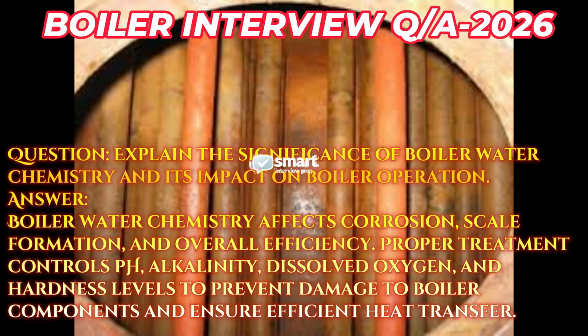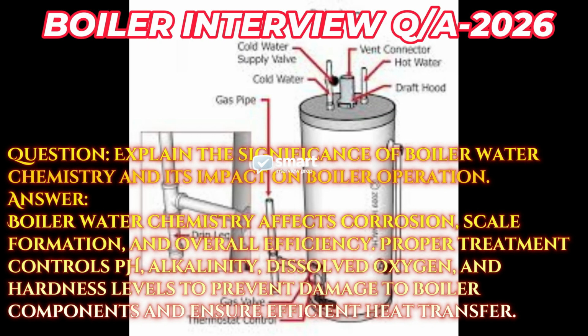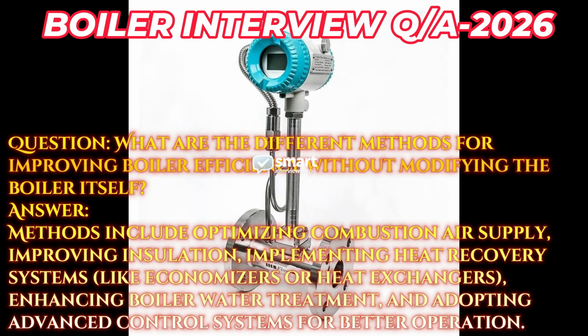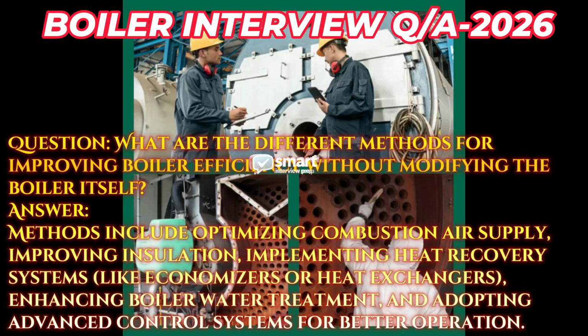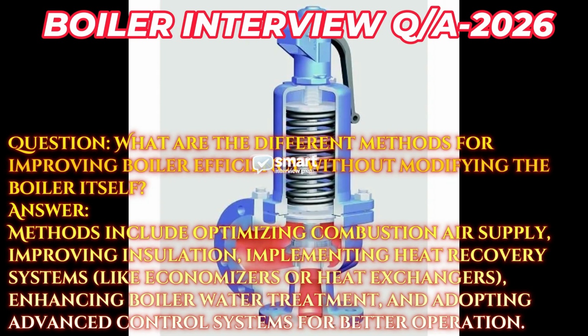Proper treatment controls pH, alkalinity, dissolved oxygen, and hardness levels to prevent damage to boiler components and ensure efficient heat transfer. Question: what are the different methods for improving boiler efficiency without modifying the boiler itself? Answer: methods include optimizing combustion air supply, improving insulation, implementing heat recovery systems like economizers or heat exchangers, enhancing boiler water treatment, and adopting advanced control systems for better operation.